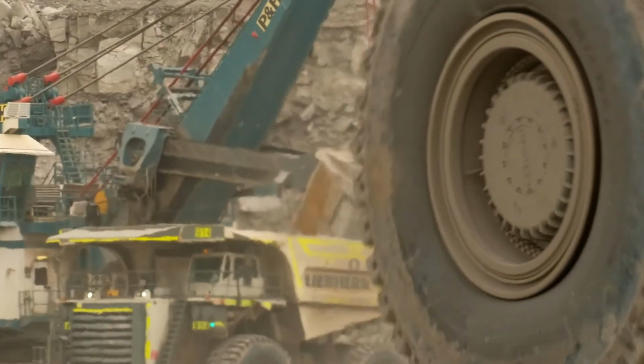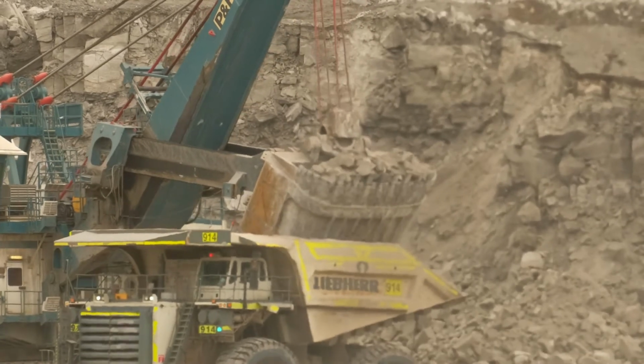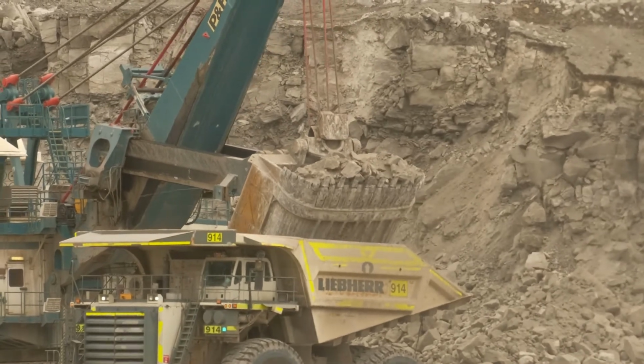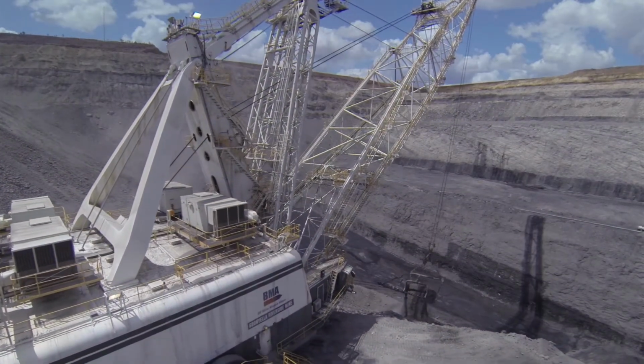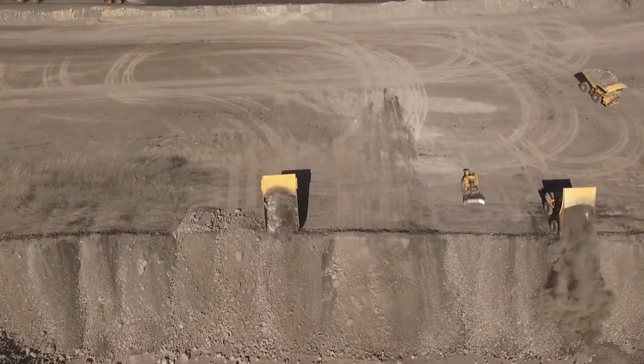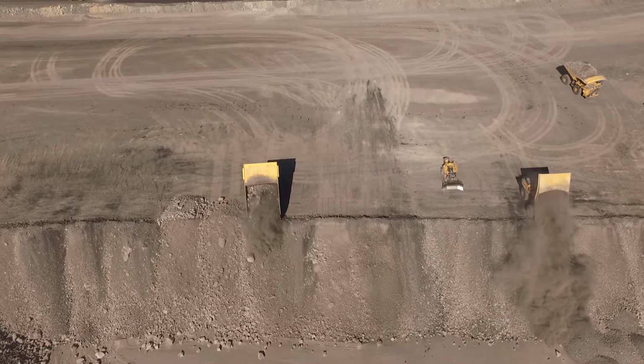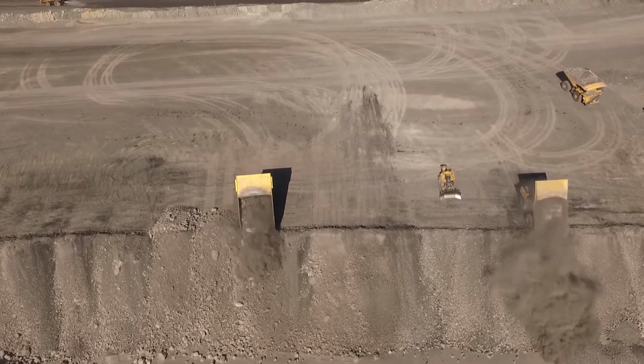Mine plans should include information on the type of equipment being utilised to execute the design, such as which horizons will be excavated by truck and shovel, and which will be excavated by dragline. Dump designs should indicate where waste material will be sourced from, so that the design process can accommodate extremely weak or weathered material.